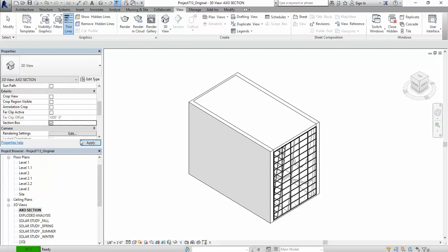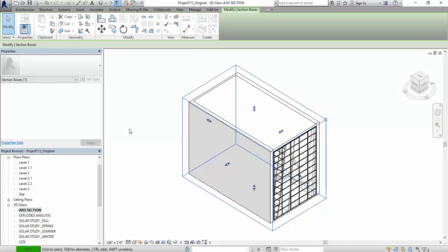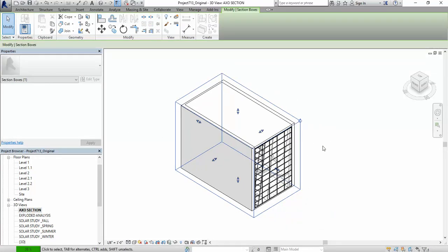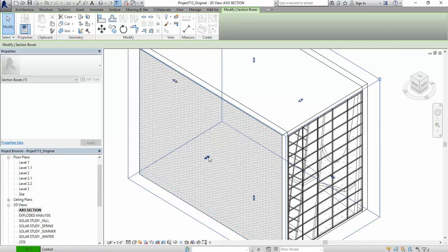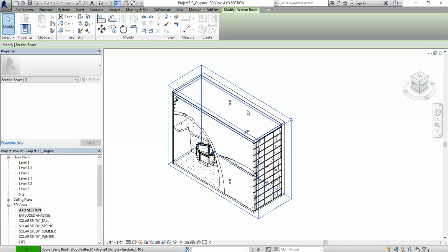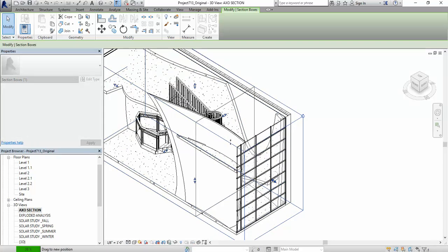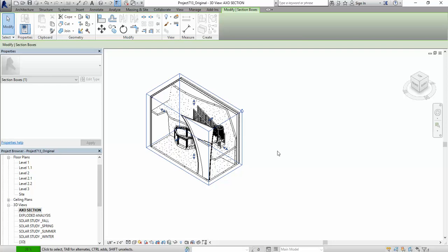As soon as you click that and you apply, this box that acts very, very similarly to the clipping plane in Rhino appears, and it has these clips. So you can move the clips to the right and to the left, but also to the bottom and the top. So you're sectioning, basically you're building in X, Y, and Z axis.